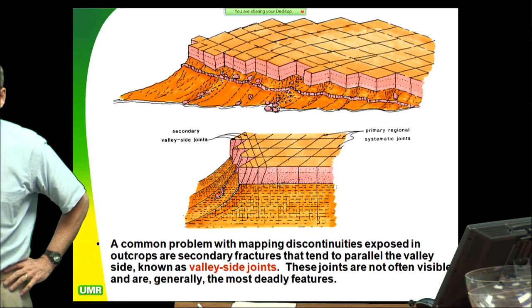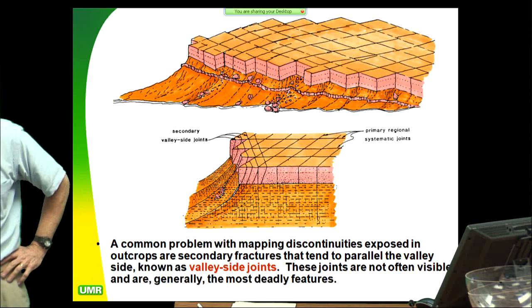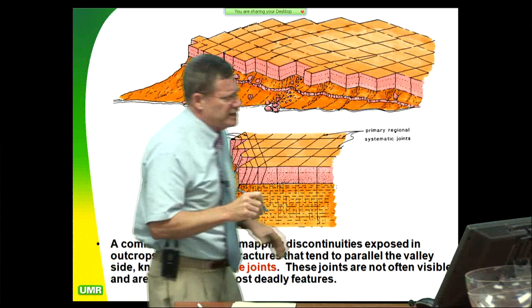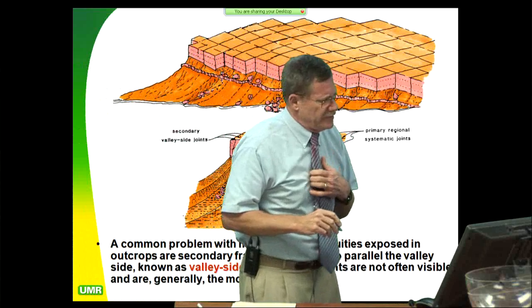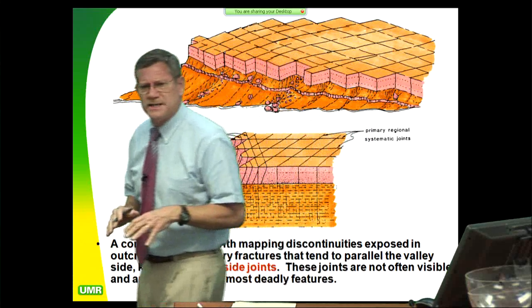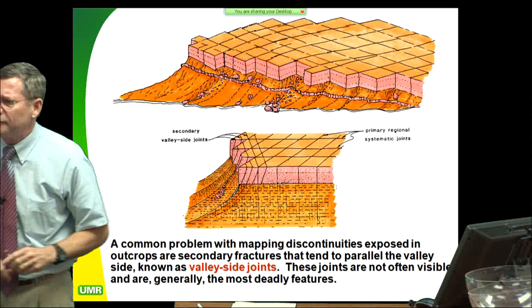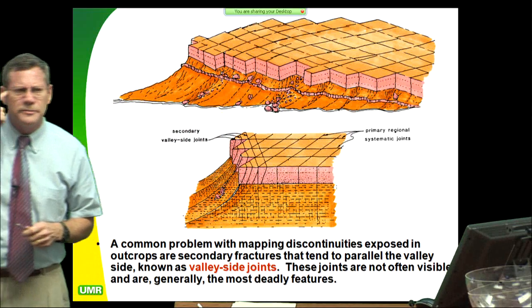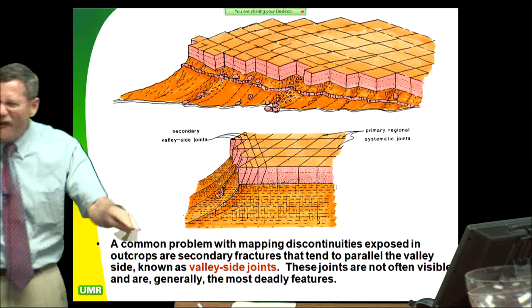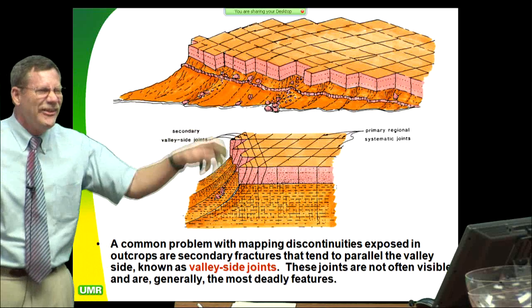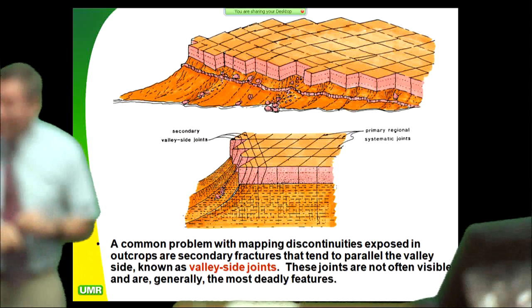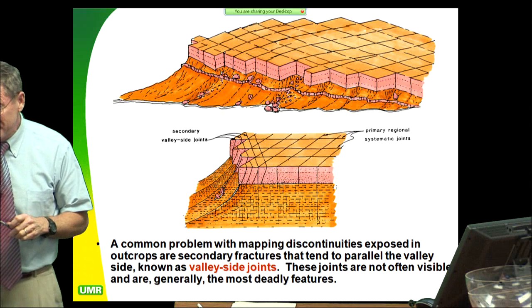Well, that was lack of appreciation of geohazards. That's what it was. How did they site the fire station? They picked the flattest spot for it. And the flattest spot was where the rock slides had come down and piled up a nice pile of rock. And nobody ever bothered to ask themselves, gee, I wonder how you got a flat spot here in the middle of the mountains. There might be a reason for it. Those are the kind of questions you want to ask yourself.